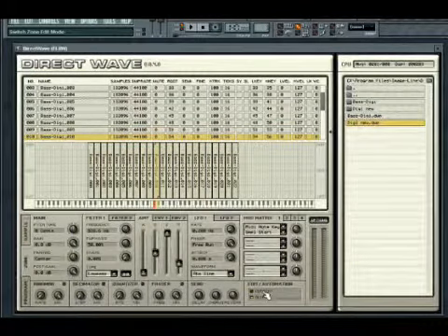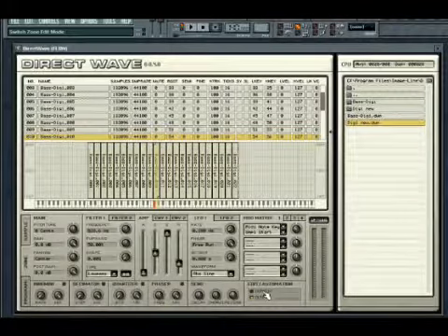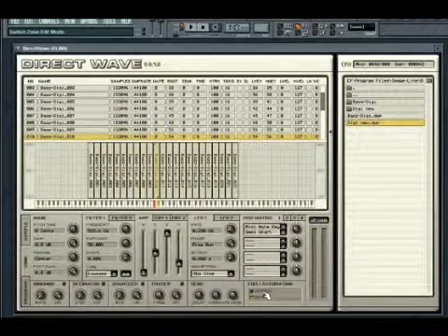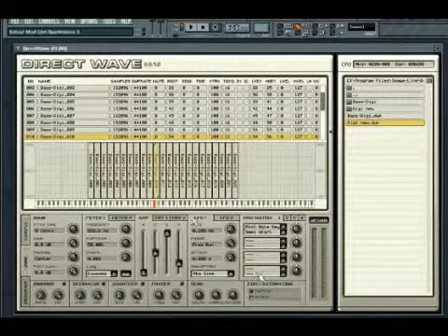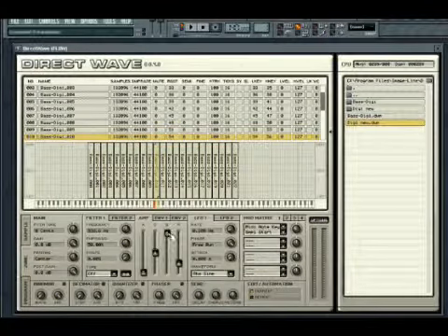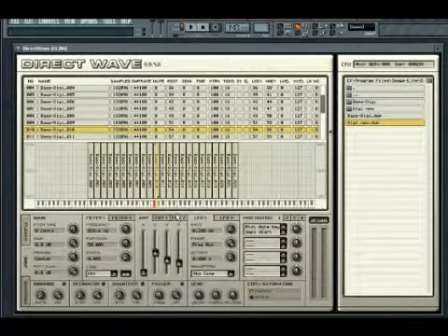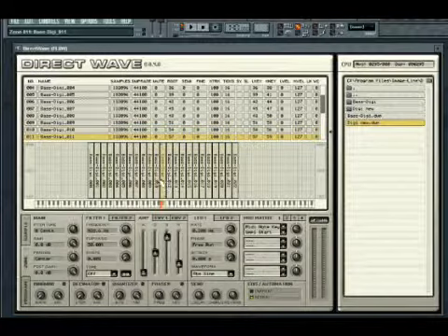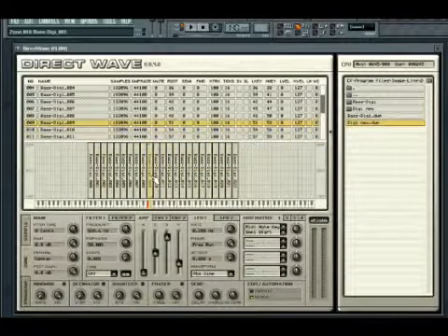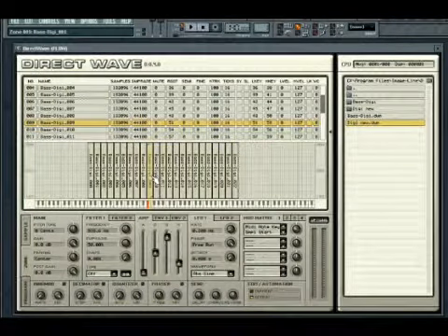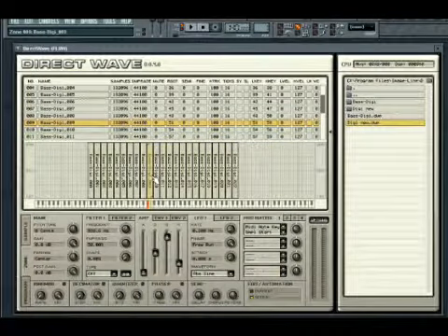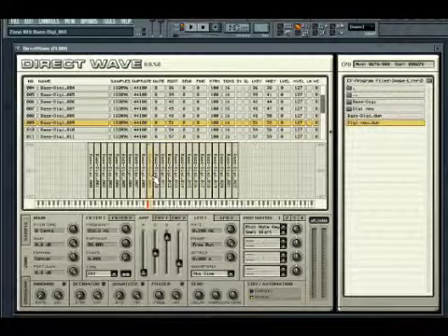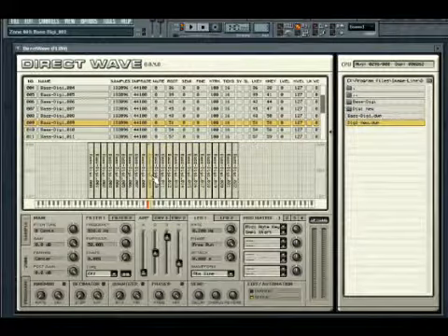Note that editing while switching between current and global modes can result in a little confusion. For example, if you select a zone and change its amp envelope sustain level while in current mode, and then you switch to global mode and change the global sustain amount, that change will then override the changes made in current mode. However, changing a setting in global mode does not then override all other settings made in current mode. Perhaps the best practice would be to initially make all alterations in global mode and then go back and edit individual settings in current mode.